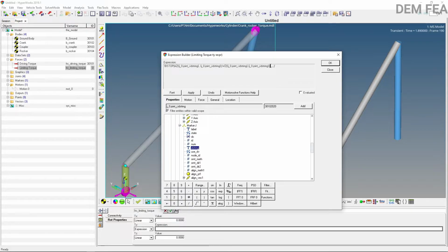And now the next thing that we want to do is to put our deflection angles, the displacement, the upper bound and the lower bound. So I want it to go by 15 degrees. So we say minus 15, this is the lower bound, times pi, so that we can convert it into radians, over 180 degrees. We are converting into radians because you cannot multiply degrees and length directly. You have to convert it. Now the other one is 15 times pi, that's the upper bound, over 180, like that.